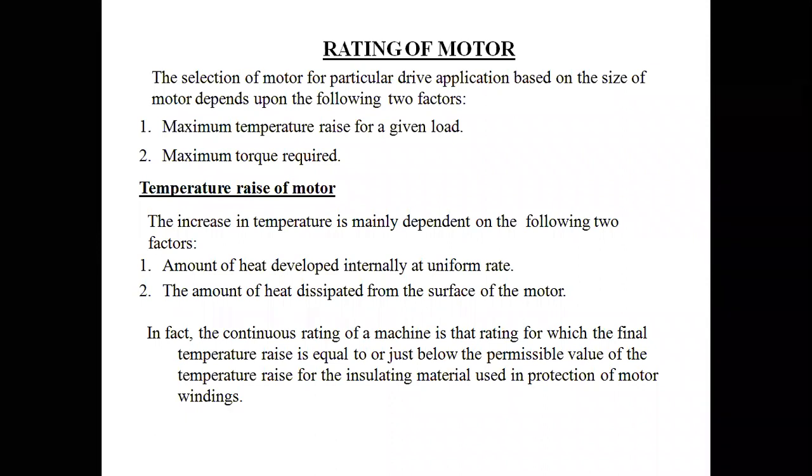This selection of motor completely depends upon the size of the motor. For domestic purpose, we are going to use just a small motor, which is used to fill the overhead tank. There we don't need any high voltage and high size of motors, high capacities. So depending upon your supply to the household, that is single phase 230 volts, single phase 50 hertz AC supply at around 6 to 8 amperes. For three phase supply, it is 415 volts, 50 hertz, and 8 to 12 amperes.